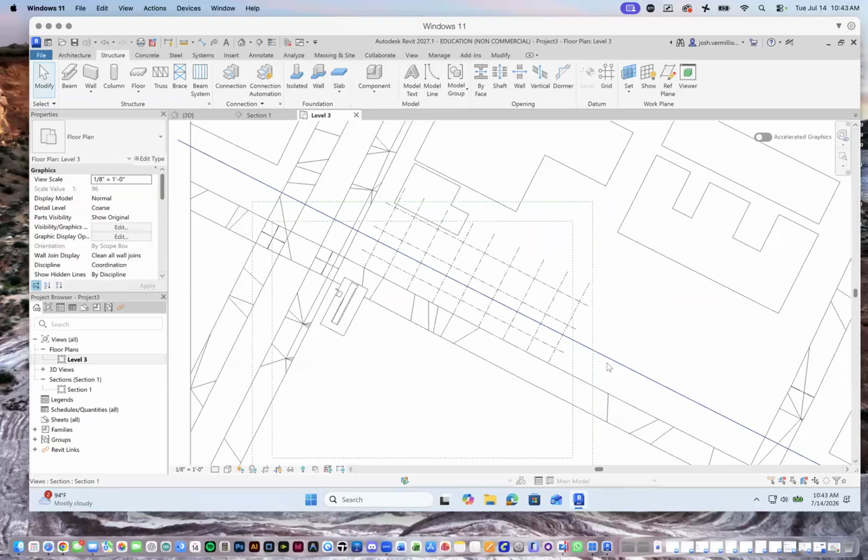And then when I pick that, it starts to give me all the standard measurements, right? So maybe I could pick a W22 by 18, which means that it's 22 inches deep and it weighs 18 pounds per linear foot. And I can start to pick and choose from a standard set of components and start to build a frame that has the economy of scale from the production logic baked into what you're actually modeling, right? So again, we'll cover more of that tomorrow in our demonstration.